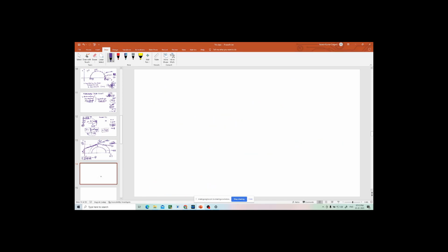So now what do I want to tell you? Some insights into this, again, Mohr circle. See, this is very important. Mohr circle is always very important. So we know there is a failure envelope. Now let us say this is the stress condition in any soil sample. That means all the planes in that soil sample are subjected to these kinds of stresses. So all are well within this envelope.